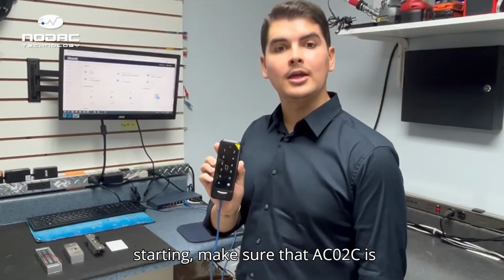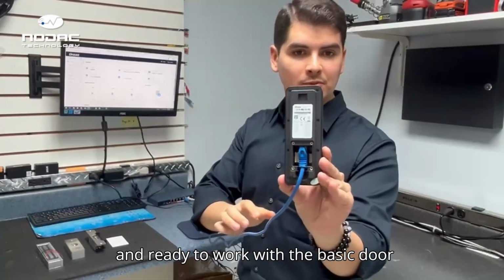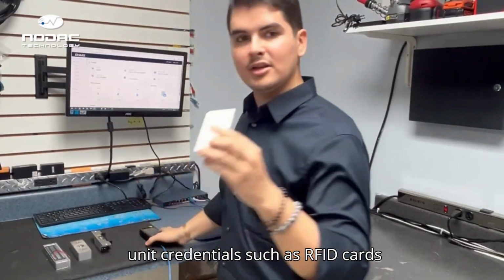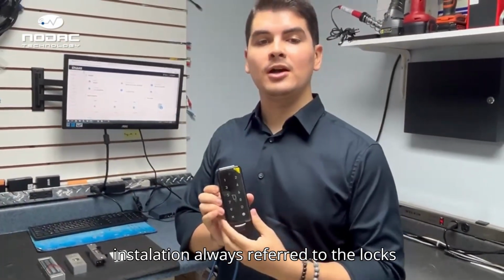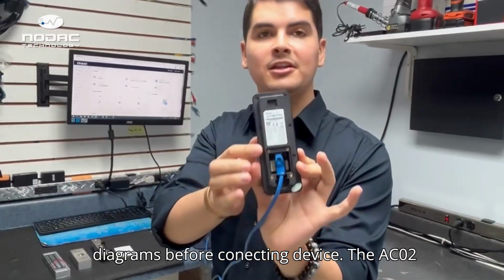Before starting, make sure the AC02C is powered, connected to the local network, and ready to work with the basic door control accessories: lock, the exit button, and user credentials such as RFID cards and PIN codes. For a clean installation, always refer to the lock type, power requirements, and wiring diagram before connecting the device.